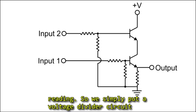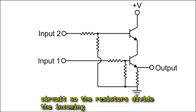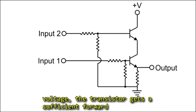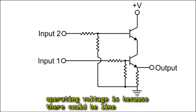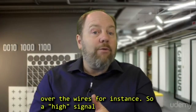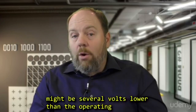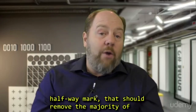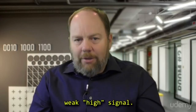So we simply put a voltage divider circuit on the input of the transistor, and we design the circuit so the resistors divide the incoming voltage, so that right around the half of the operating voltage, the transistor gets a sufficient forward bias to turn on. Now the reason I say half the operating voltage is because there could be line loss from the upstream circuit, a voltage drop over the wires, for instance. So a high signal might be several volts lower than the operating voltage, but it is a high signal. So if we aim for the halfway mark, that should remove the majority of any false signals, but still allow for a weak high signal.